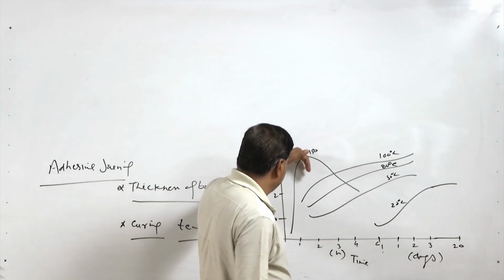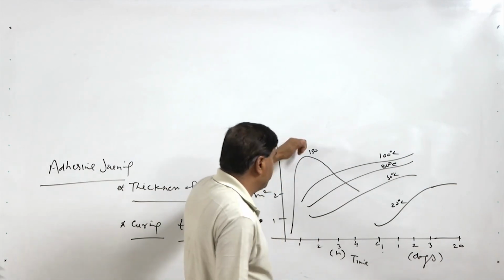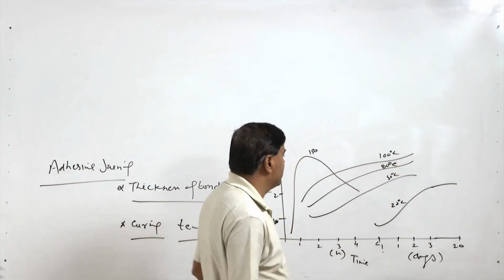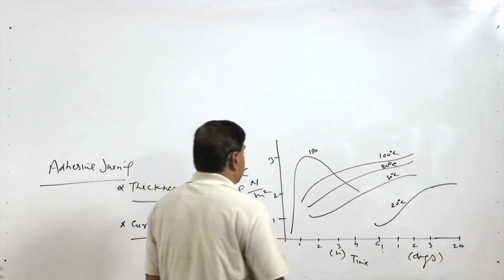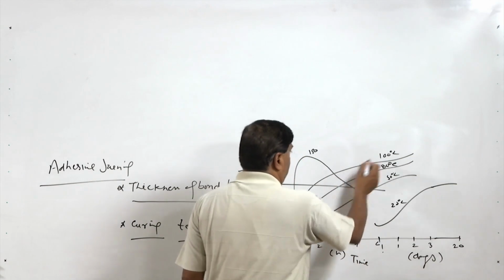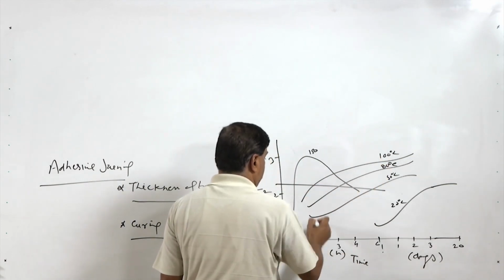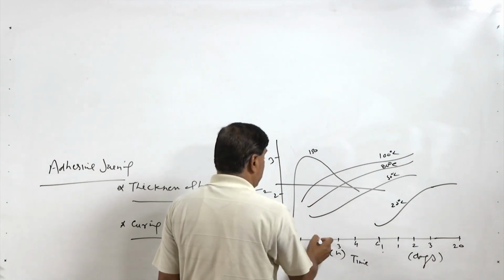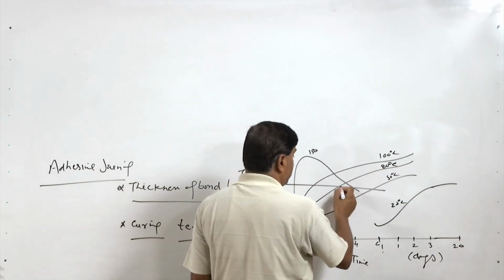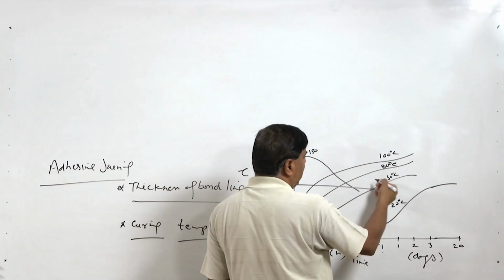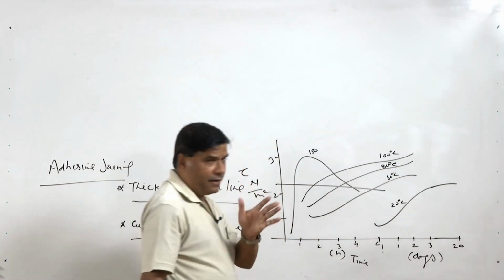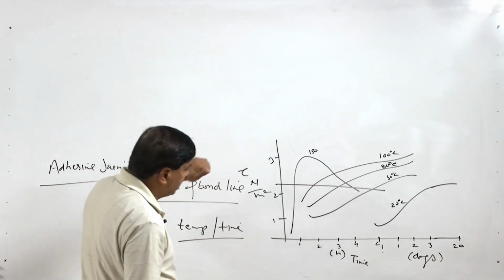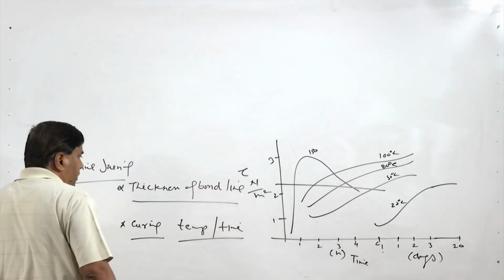It is, say, 1 or 1.5 hours at 150, and then it keeps on increasing with the increase in temperature for the same strength. For example, here at 100 degree centigrade we can get the same strength after 2 hours, while at 80 degree centigrade it is 3 hours, and likewise. So, at a higher curing temperature, the same strength can be achieved in a shorter curing period.